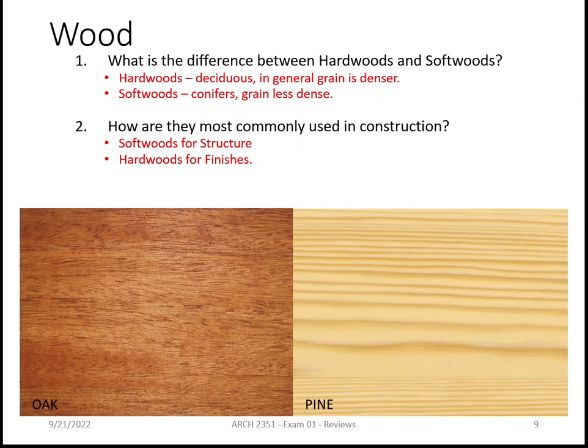It's usually denser, and therefore, usually, hardwoods are denser than softwoods. That means they're harder. That's the reason they're preferable for furniture, because if you hit maple or oak, you're not going to leave a dent in it. If you've got pine there and you drop something on it, you're going to have a pretty major dent in it, because it's just not very dense.